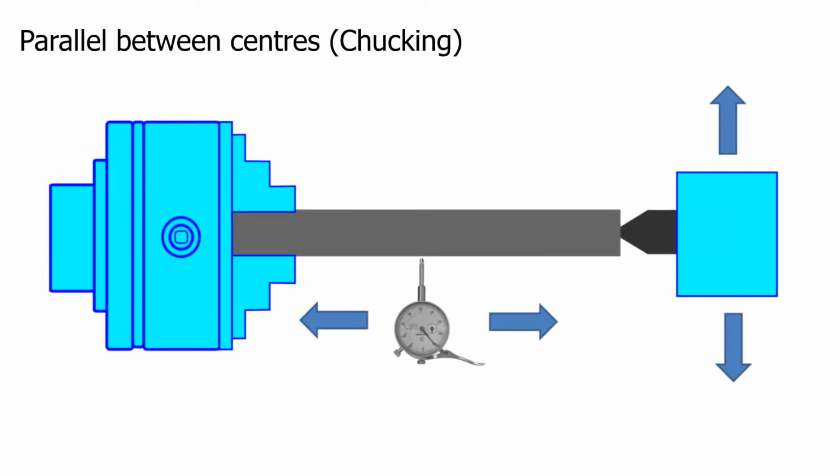Even if you are using the chuck with tailstock support, a misaligned tailstock can still cause tapers, concave and convex profiles along the length. Check for parallel and flexing with a precision bar. You may have to use a steady if the bar is too long to eliminate any flex.